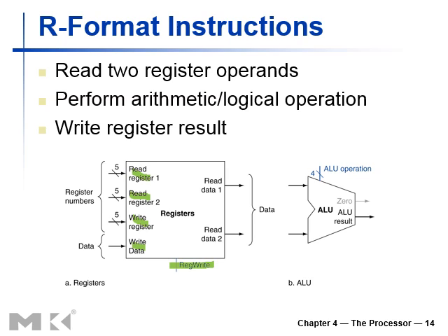If you remember that in our machine code, the terms that have been appearing as RS, 5 bits RS, RT, and RD basically. So those bits basically are being mapped here on these dedicated lines. Then if you have to write the data into a register, we have got a 32-bit interface here that brings the data back to the register. And the address is being specified by this, or we can say that RD.